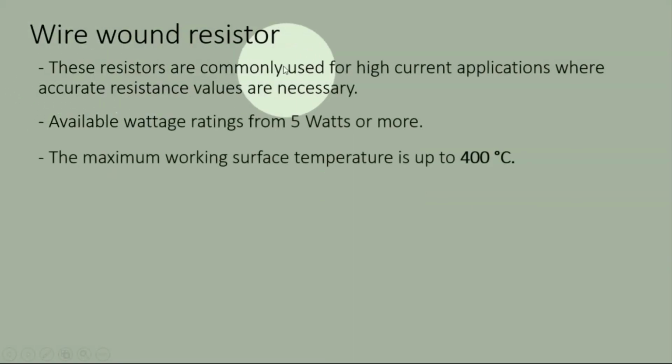These resistors are commonly used for high current applications, and also where accurate resistance values are needed. You can have this device from 5 watts or more, and if you are working at a surface temperature of up to 400 degrees Celsius, the Wirewound resistor is the best device.